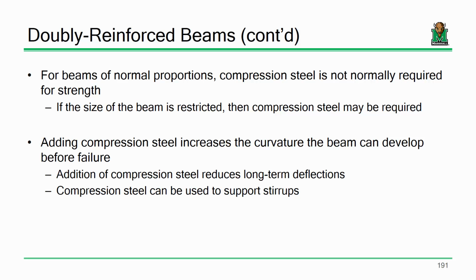One of the things about concrete that makes it a more difficult material to assess than something like steel is that concrete's material properties tend to change over time. Concrete on day one does not behave the same as concrete 10 years from now. And anybody who's had any experience with that will be able to testify to that. Concrete experiences some material-related phenomena that change its properties over time. One of those is a phenomenon called creep. Has anybody ever heard of the term creep?